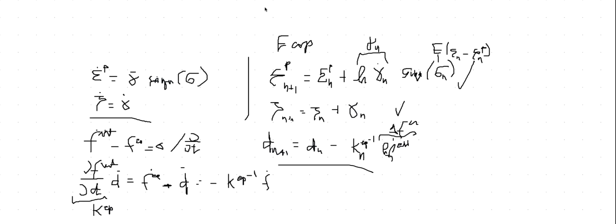So let's say Kn elastoplastic, this is what you can use in your computation. For this particular element e, it would be the integral over omega e of B A, this is dN dx, times C elastoplastic at time Tn, times B B, and this will be it.